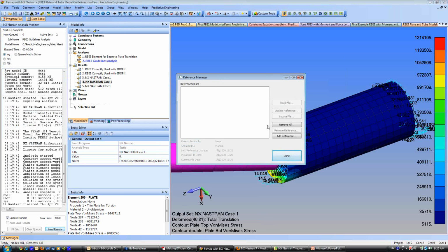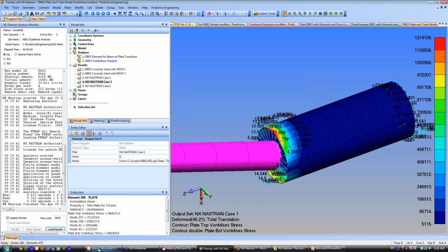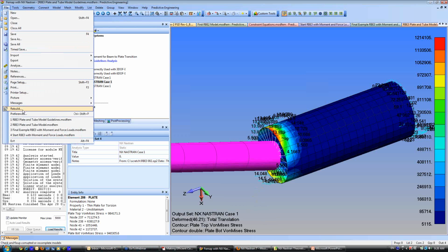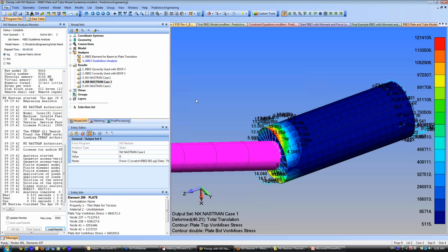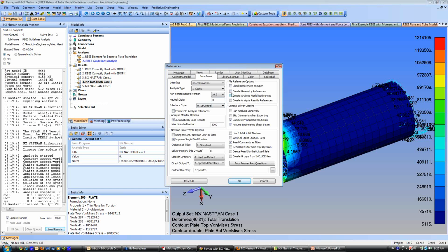And if you update that geometry, bring in a new piece of geometry, it logs it into the model file. And let's say you wanted to update or move it in, it will always check. It always creates a link out there. For my models, I bring in a chunk of geometry, and then it's hasta la vista. I'm done with it. I'm always doing other things with it. I don't like to have that tied around, and it clutters up the database, and it always pings me and asks me every time if I want to update it. So this is something I always turn off.